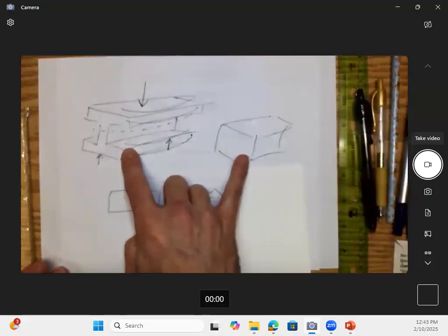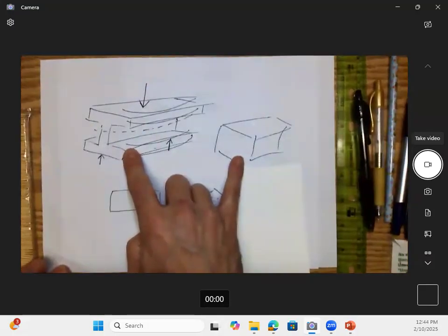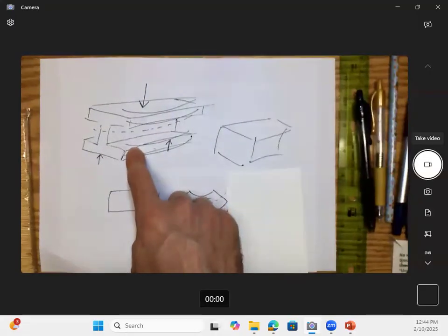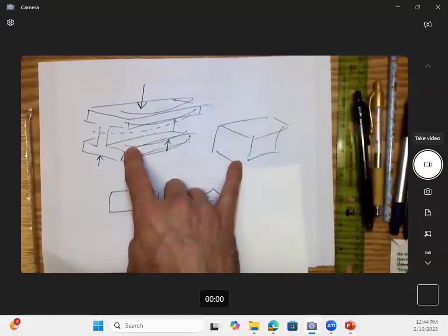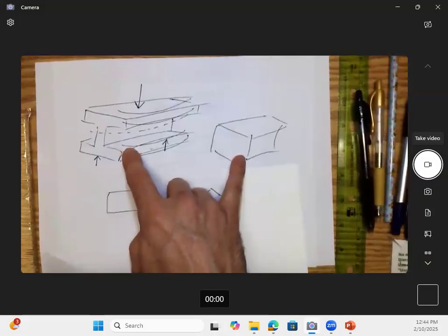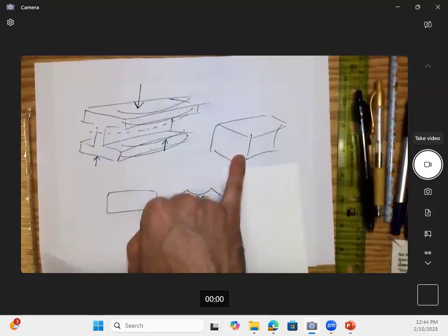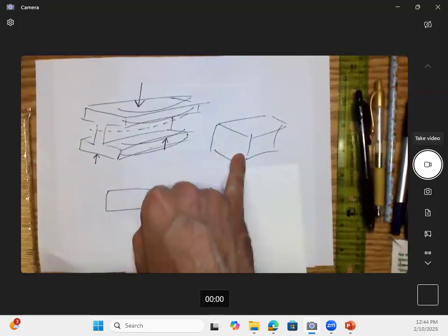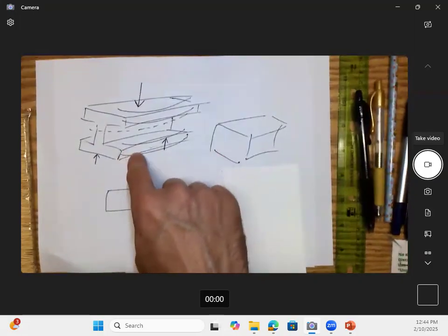Well, one is that steel is fairly expensive compared to concrete, so you only want to use as much steel as you need. I see that this one, where I've carved out the sides, is a lot less material, but it's nearly as strong. These two might have pretty similar strength, even though this one's more material, more costly, and also heavier too. And that's not necessary. So let's go with this shape.